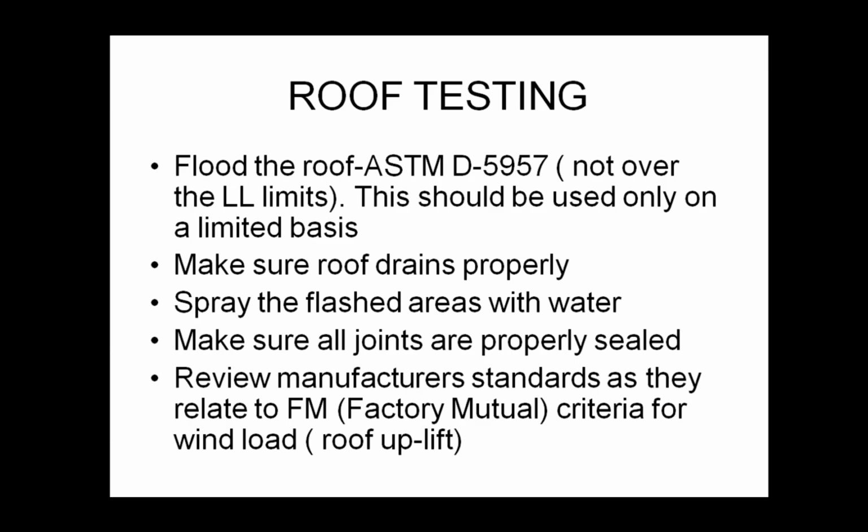It's like a live load test of the roof, by flooding the roof and making sure that there are no leaks. That's a great test, but what happens if you do weaken your structure by doing this and it just doesn't fail? You're that much closer to eventually failing. So it should be used sporadically, only where necessary as required by a spec maybe, but it's probably a little further than you should go in terms of testing a roof installation. We like to say use the first rainy day or first heavy storm to really test out your roof.